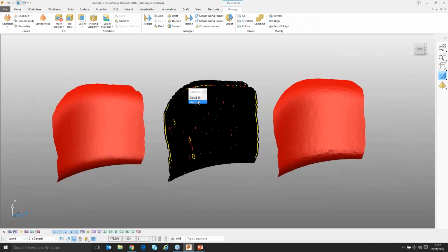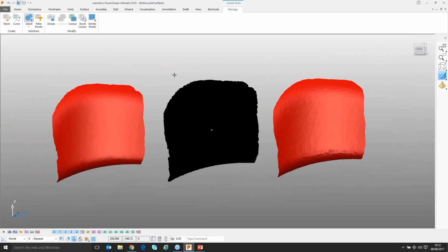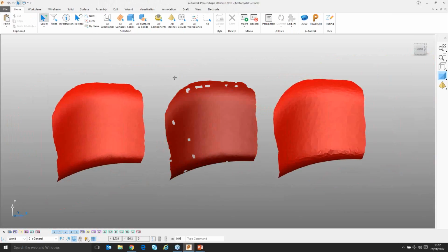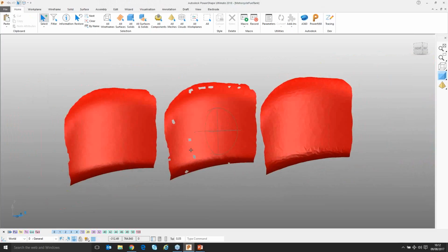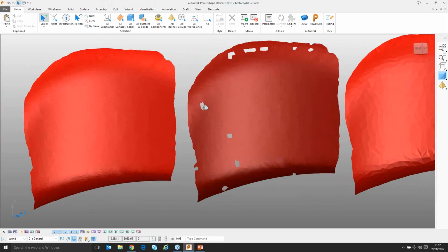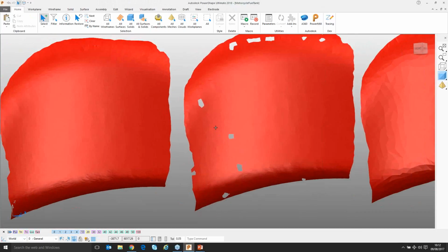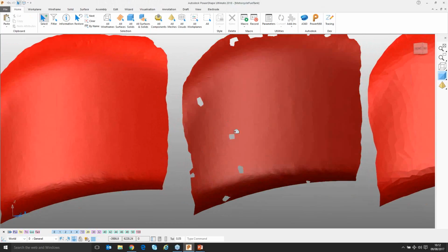So now let's take that mesh. In fact, what I'll do is I'll select the cloud itself and just delete that. So what can we see? Well, we can see that the hole fill hasn't been as successful. So there are areas where 5 millimeter didn't quite close off the gaps where the point spacing is bigger than the 2.5 that we, or the 0.5 that we went for.